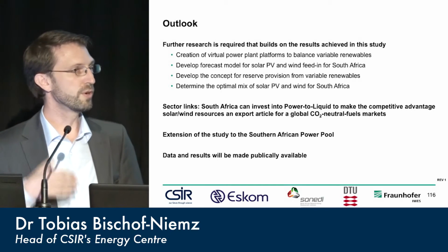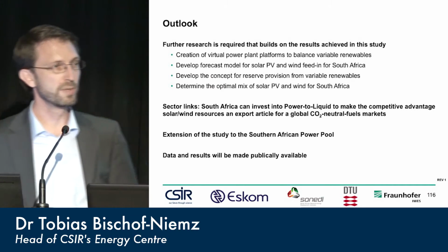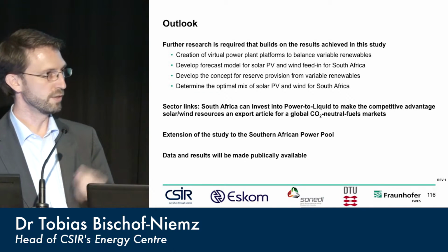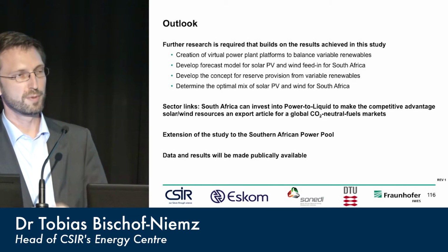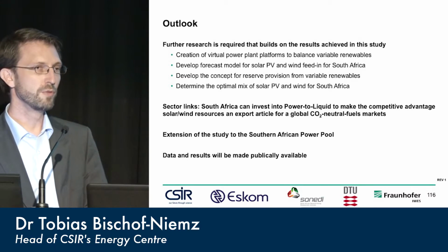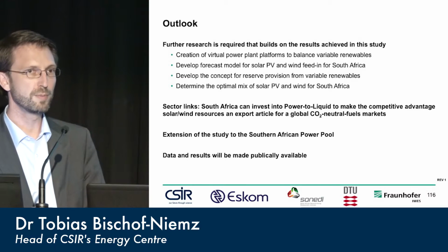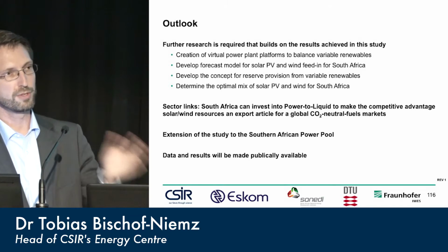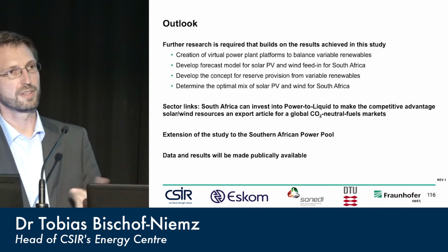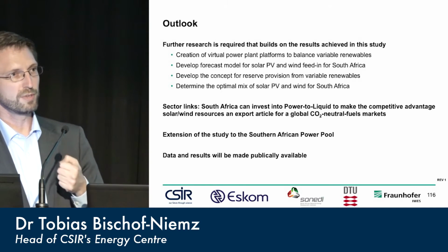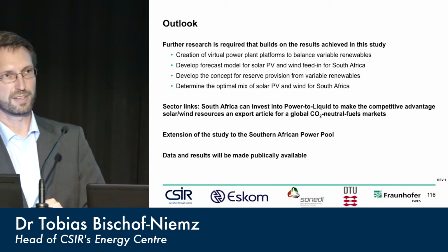Another question, when you go into a very high share of variable renewables, is how much the renewables themselves can provide and supply reserve capabilities. If you think especially of PV, the supply is very predictable, very smooth throughout the day. So if you know what's happening with the PV supply during the day, then you can use the PV fleet and instantaneously curtail it to the needs of the system operator.